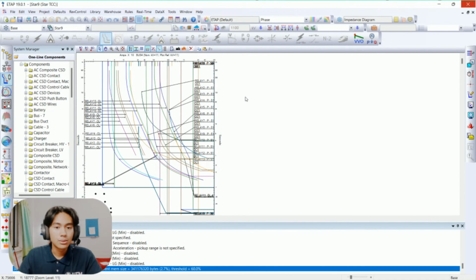So to conclude all of this, I can say all these relay characteristics I assume as a standard inverse characteristic, that is called an IDMT relay, whose operating time is approximately inversely proportional to the fault current.